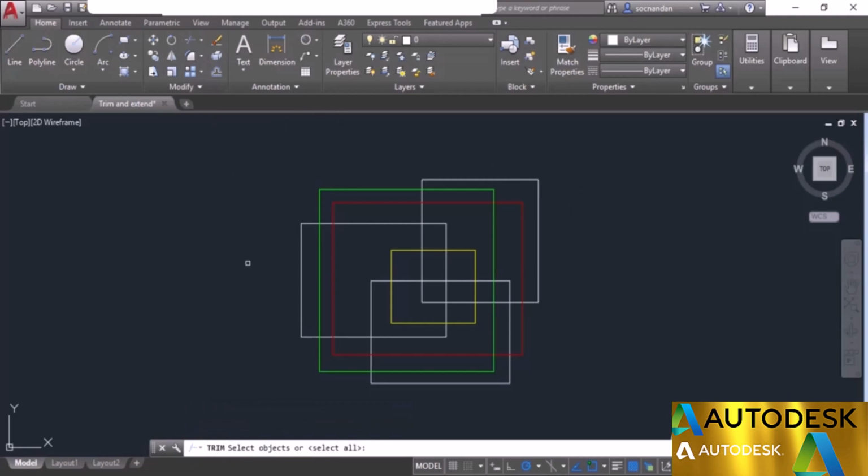In the previous cases, we have directly pressed enter, and by pressing enter, we have selected all of the objects in the drawing area. And by selecting the objects, we were essentially allowing the trim tool to trim objects with the very next boundary. But in this case, we can select the boundaries which will be used for trimming.